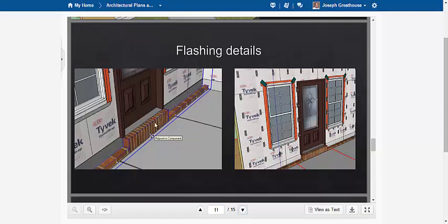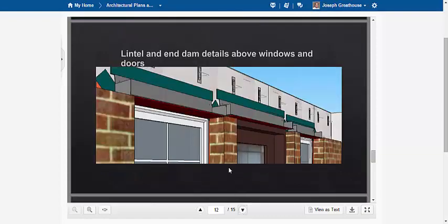And when you see brick that is stood up like this, and the skinny part faces out of the brick like this, that's called a soldier course. A sailor course would be to turn those bricks 90 degrees, so you get the wider face pointing out. So again, some good Tyvek, some good flashing details that are here. We'll discuss more of that in that residential construction class.